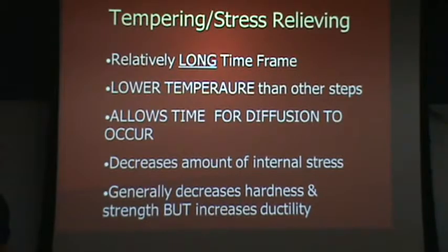Right? If I have a shaft that's several hundred inches long, and it's 10 inches in diameter, it's probably not going to be straight when I'm done with the quenching and tempering operation. But I need it to be straight. If I've got to put it into a machine tool, the machinist wants it straight. The customer is going to make, say, a ship shaft out of it. They want it to be straight. So we have to plastically deform it. We have to bend it back to being straight.